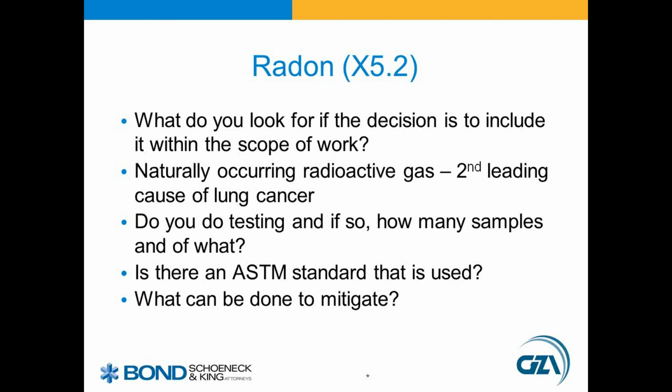E1465-08A is the standard practice for radon control options for the design and construction of new buildings. And if you have an existing building you need to remediate or mitigate radon from, you can refer to E2121-13. Mitigation is relatively easy and fairly inexpensive, and usually involves just installing some PVC pipes under the basement floor slab and venting them to the outside with a powered fan.